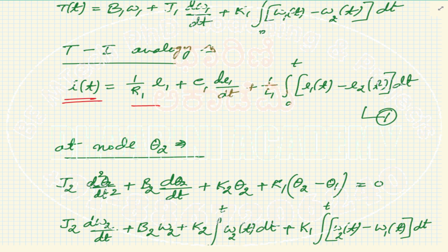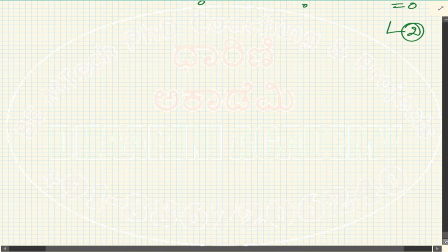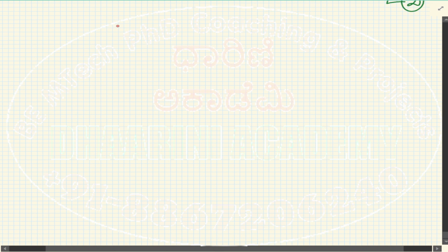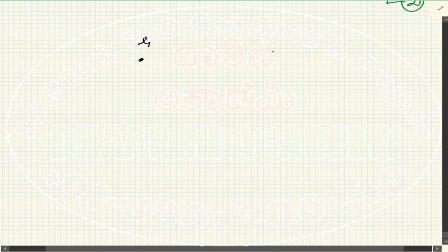So it depends upon the analogy. As soon as I see that there is a current analogy, I should understand that the circuit which I'm going to write will have parallel branches. The components are not in series. Every component will be present in the parallel format. So now the node gets replaced by E1. One node has a node voltage E1. This is node analysis, not the mesh analysis. The previous one was loops, right? So we used to write loops, now it becomes node analysis. Equations correspond to each node.